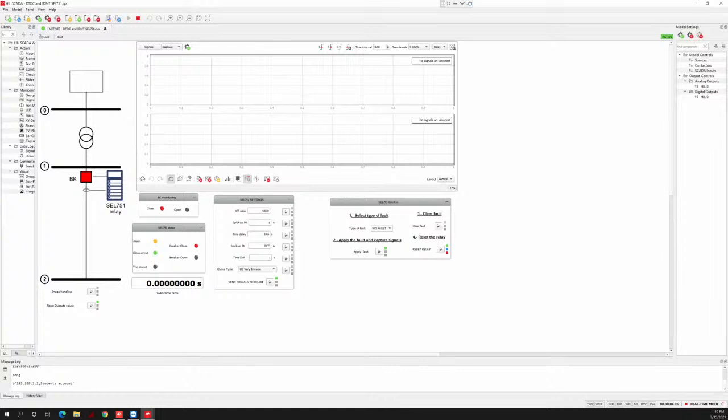Okay, let me go back here. This is the bay, this is the meter, this is the phasor of the voltage. This is 11 kV, 1100 something. Okay, could you see here that you can see the voltages, you can see the currents, you can see the angles, and this is perfectly a three-phase system, okay?